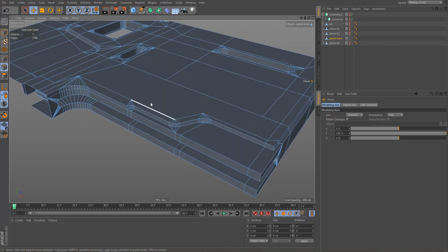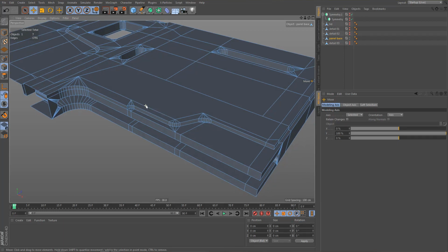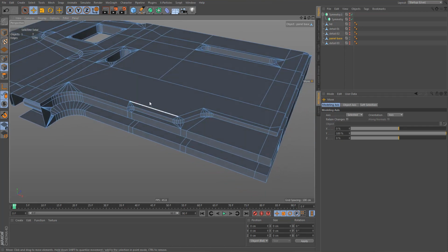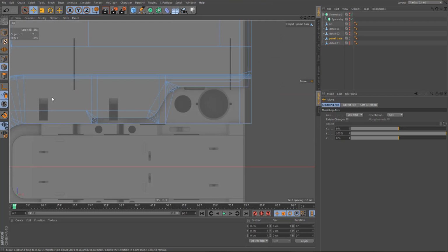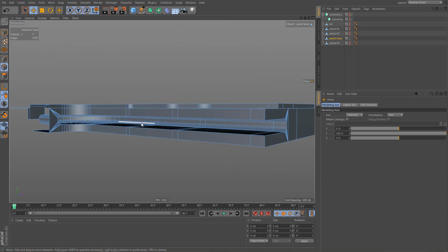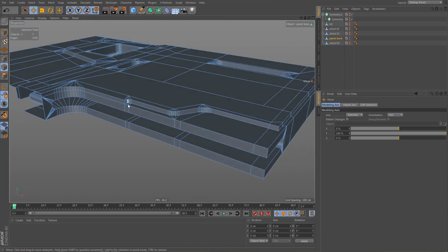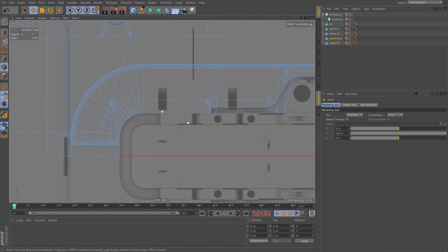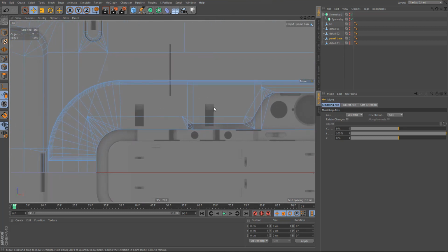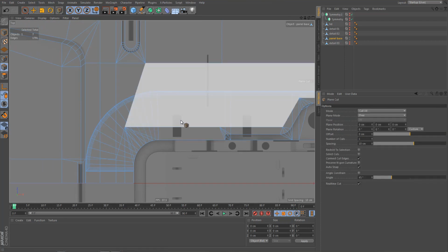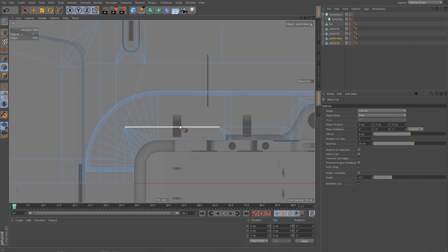This is a bit tricky, and also it's kind of important in which order you do things, because certain things will be more difficult if you don't do them in the right order. For example, putting in those square holes is more work if you don't have the edges down here beveled when you put those holes in there. So let's see what we can do here. So next we're going to add these square holes here, and I'm going to add some geometry before I use some cubes and a bool object to get those holes in there.